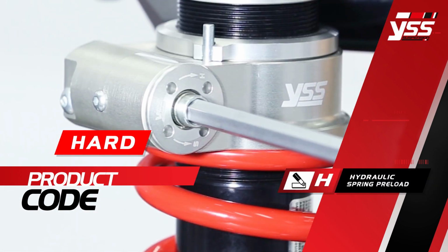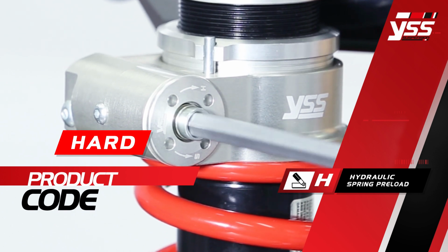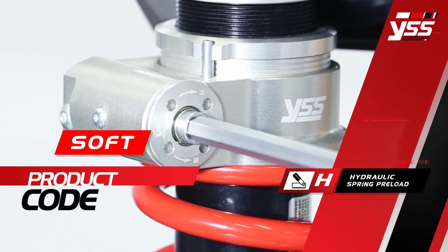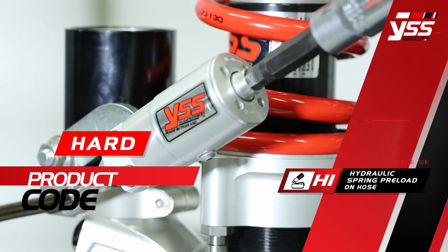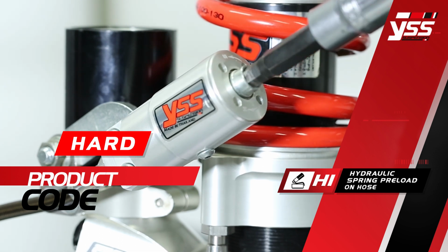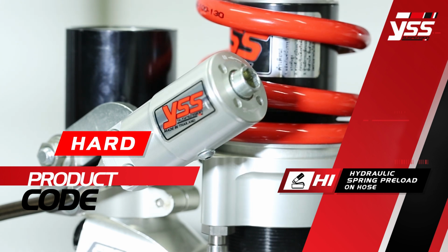H: Hydraulic spring preload. This feature uses a hydraulic system to adjust the spring. Turn the knob towards the plus sign for harder spring. Turn the knob towards the minus sign for softer spring. H1: Hydraulic spring preload on hose. The movable hose is convenient to adjust preload without a spanner and dismounting.